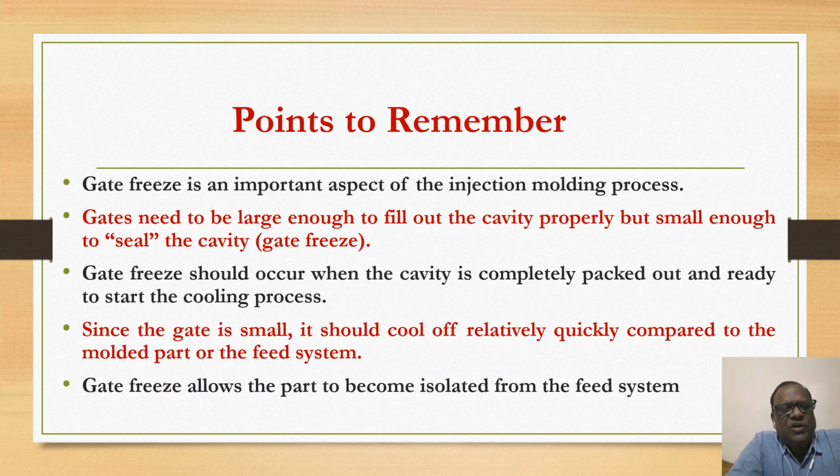The other thing to keep in mind: gate freeze is an important aspect of the injection molding process. It is required, but as I told you, it should not freeze off before the cavity is filled. So gates need to be large enough to fill the cavity properly, but small enough to seal the cavity, and it should freeze once the material is filled inside the cavity.